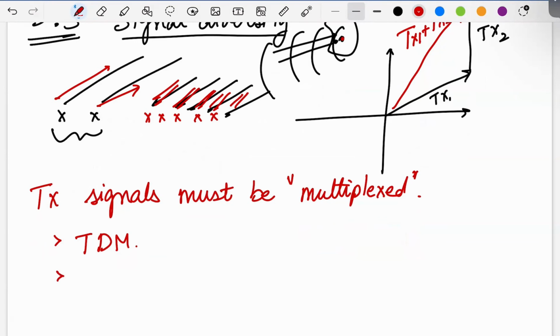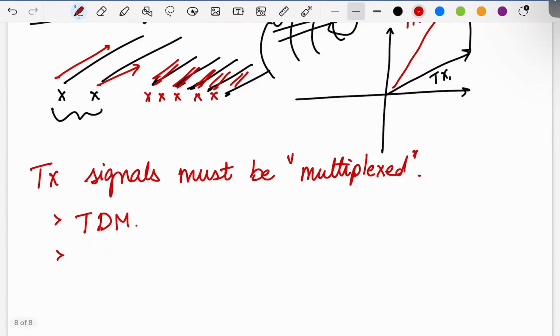And that's nice for FMCW. That's somewhat popular even, for example, if you have just a network analyzer and a microwave multi-port switch. So you can just switch between the two transmitters and all of the receivers and collect your entire signal matrix, right? Okay, that's time division multiplexing.